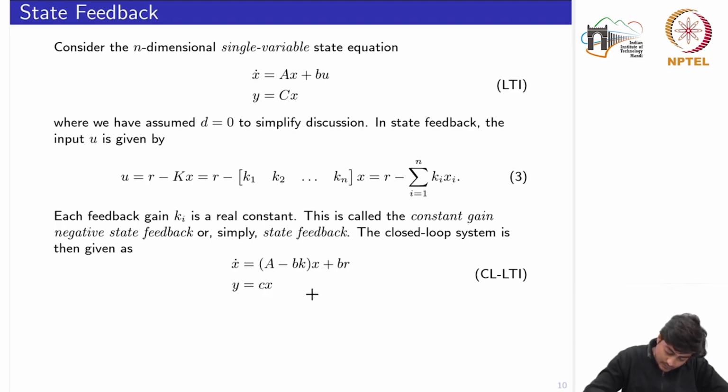So what we want to implement, if we see the state space description, is that we have the integrator 1 by s, then x dot, which is basically the summation of A times x and the gain vector B times u.